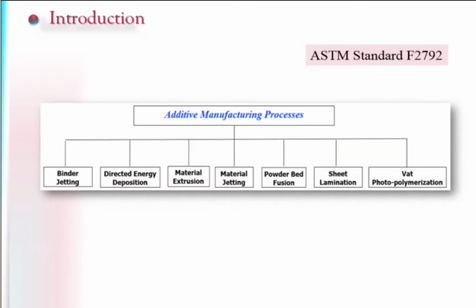According to ASTM F2792, additive manufacturing technologies can be categorized into 7 different categories, which can be better understood by following the flowchart. One of the most common materials used for the FDM process is Acrylonitrile Butadiene Styrene (ABS). ABS is a thermoplastic polymer, a material which becomes moldable at a relatively low glass transition temperature and solidifies upon cooling.